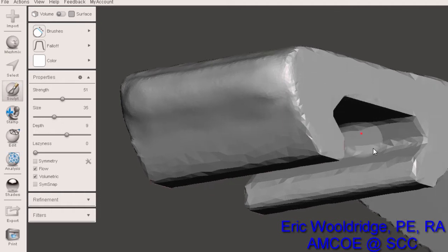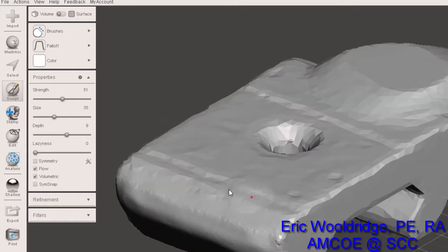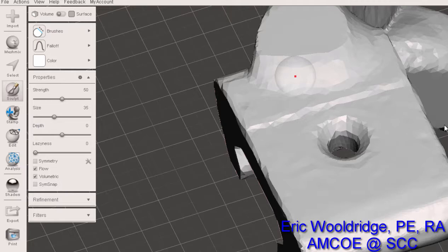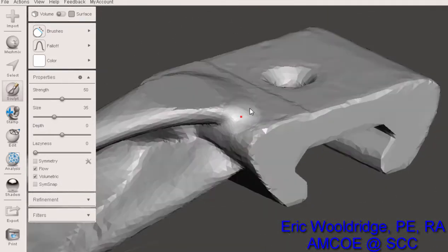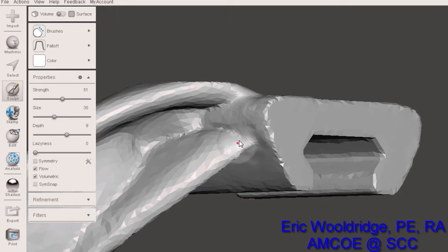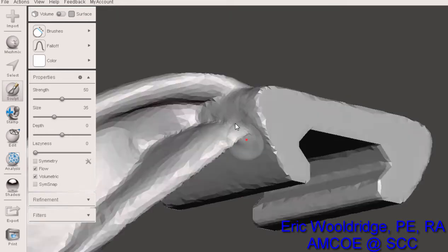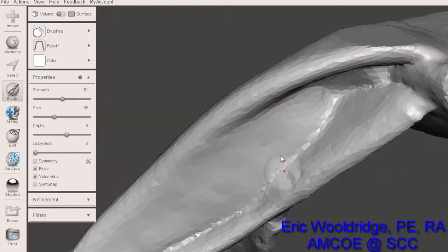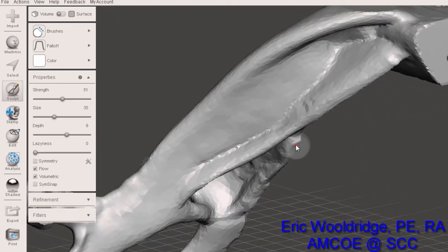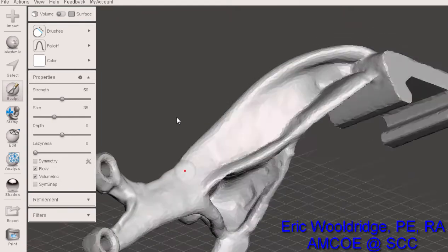Again, making sure that I don't touch anything in this zone because that's where the contact points are going to be for this particular project. So I don't want to interfere with any of that. I just want to figure out what I can fix above, smooth out, and make a little bit more realistic. I'm also taking a little time to look around to see if there's any funky joints, little sharp corners that I could probably take care of with a flattening or maybe a bubble fill. That one looks a little funky, but it's probably okay given so much material around it. And just looking for any little areas where stress might be concentrated.